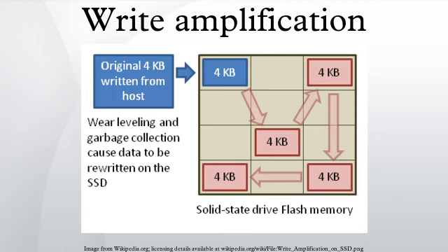Intel and Silicon Systems used the term write amplification in their papers and publications as early as 2008. Write amplification is typically measured by the ratio of writes committed to the flash memory to the writes coming from the host system. Without compression, write amplification cannot drop below 1. Using compression, SandForce has claimed to achieve a typical write amplification of 0.5, with best-case values as low as 0.14 in the SF2281 controller.